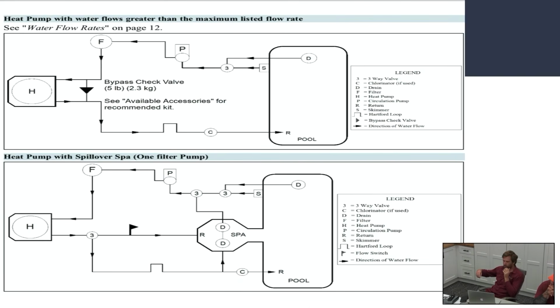The important thing to know about water flow when you are connected with the spa is that the spa has its own drain and its own returns. The returns are the jets, water coming back to the pool. So it's opposite of your AC, where what the pump intakes we would normally call the return. The return and supply is just labeled opposite in the pools. The drains are the supply, the jets are the return.